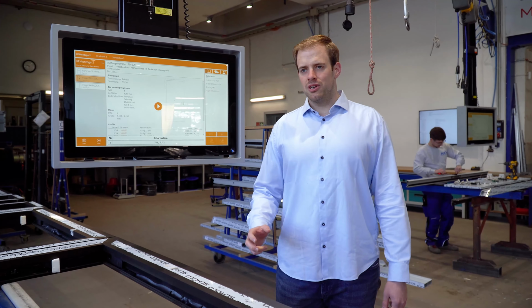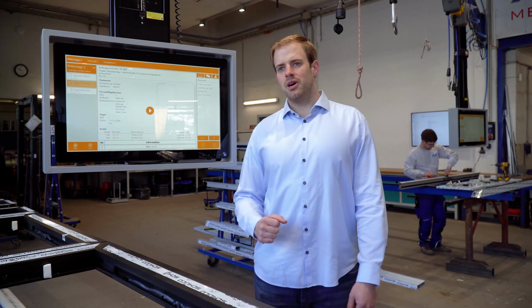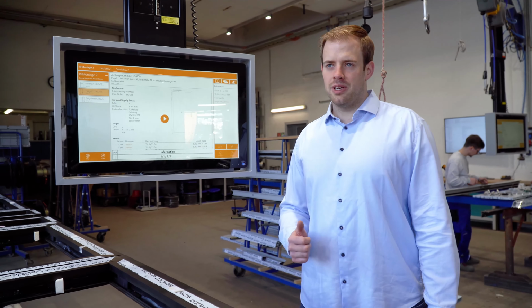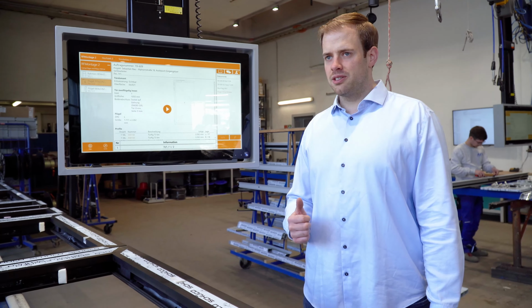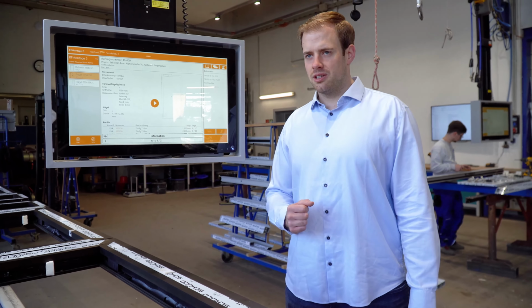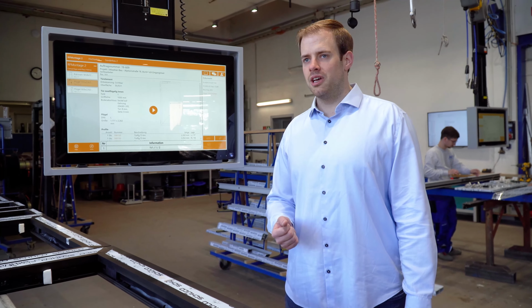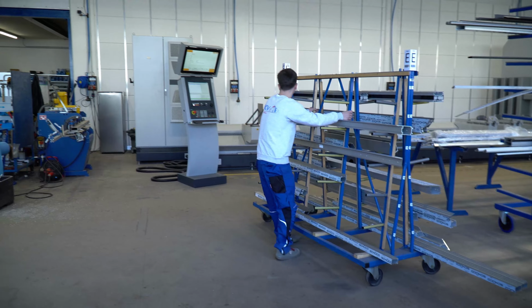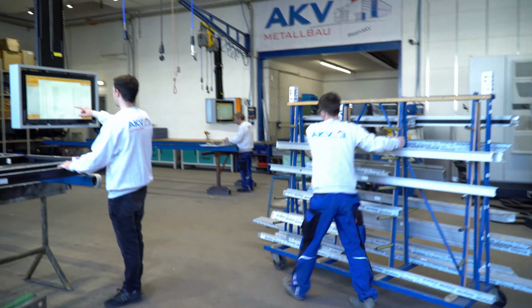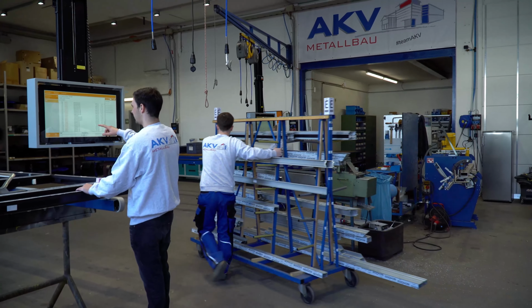Once the cutting of the individual profiles is completed and all bars have been processed in the machining center, meaning that all profiles for one element are prepared, the colleague at the respective workstation confirms this step. As soon as this happens and the element is fully completed from a cutting perspective, it appears at the next workstation, at frame and sash assembly, and later during final assembly.